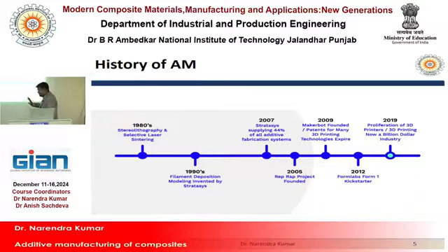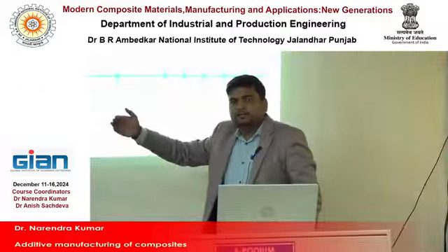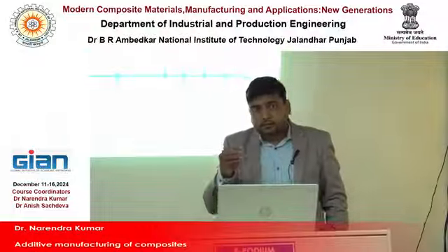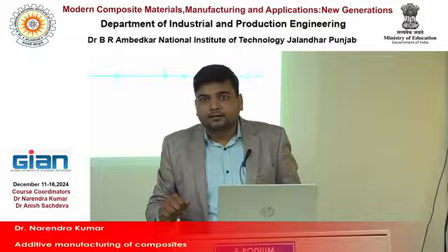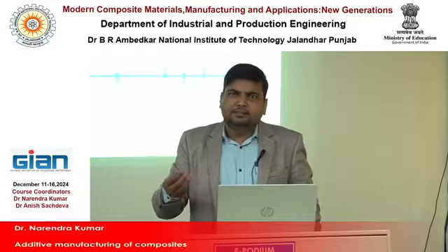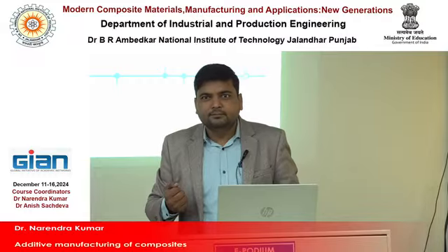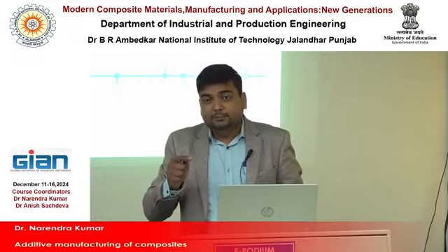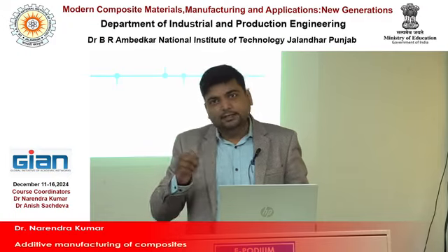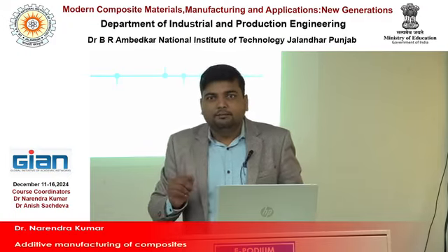Basically, DLP is similar to SLA, stereolithography. You can get a DLP printer for only 20,000 rupees, and an FDM printer for only 15,000 or 18,000 rupees. So DLP is becoming popular because of its cost, equivalent to the FDM process.